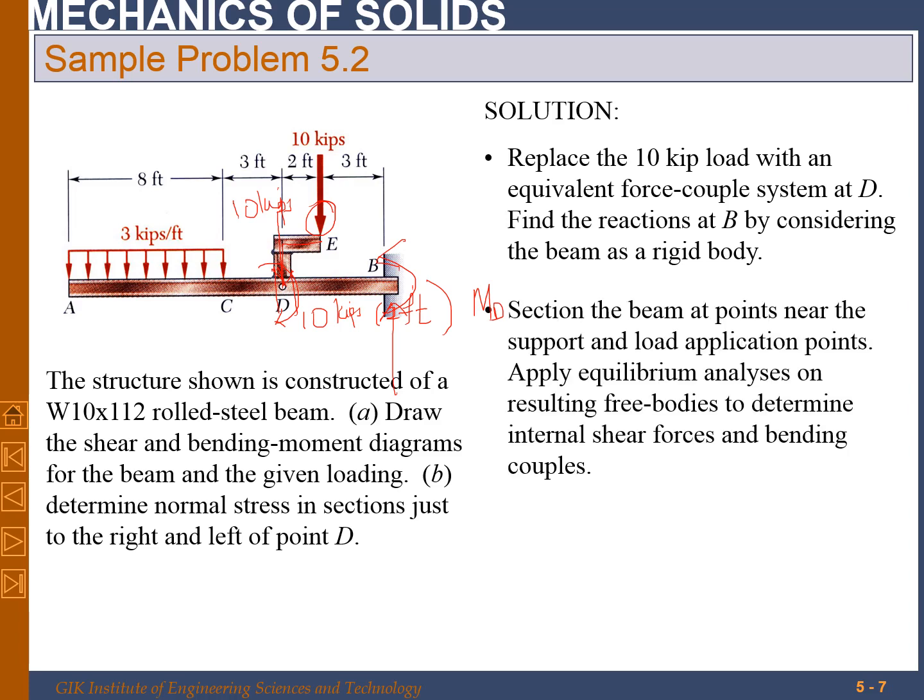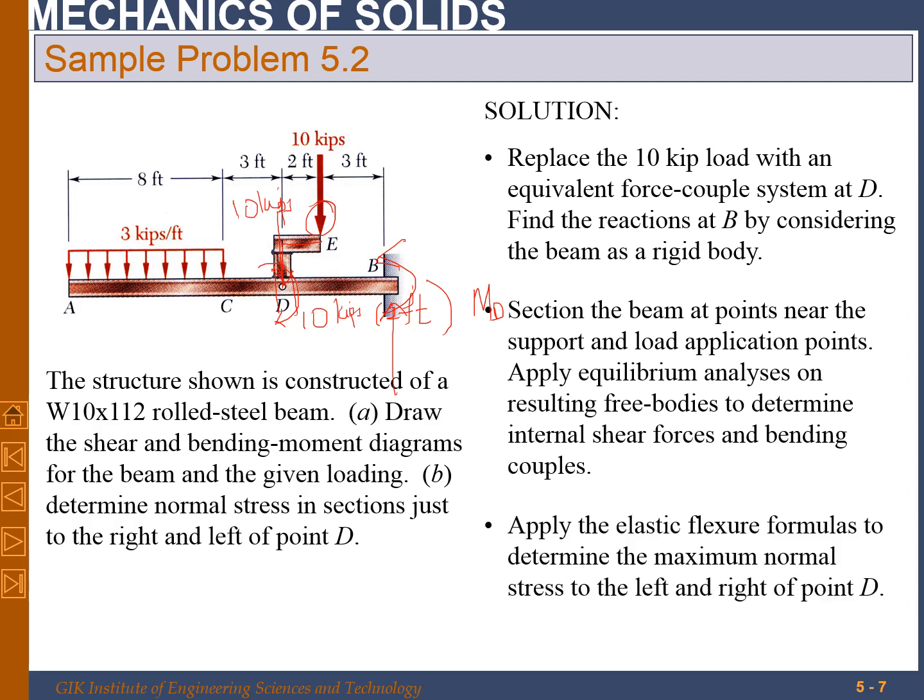Then we take a section at a point near the support and the load application point, and apply equilibrium analysis to the resulting free body diagram to determine the internal shear force and bending moment. And using that, we will draw the shear force and bending moment diagrams. And then we will use the elastic flexure formula to determine the maximum normal stress to the left and right of point D.